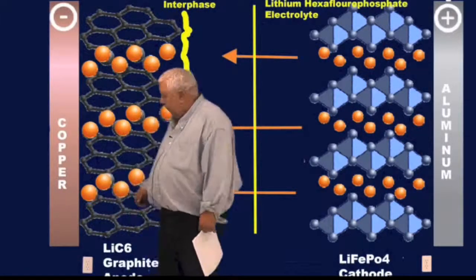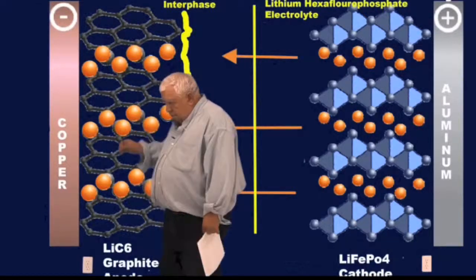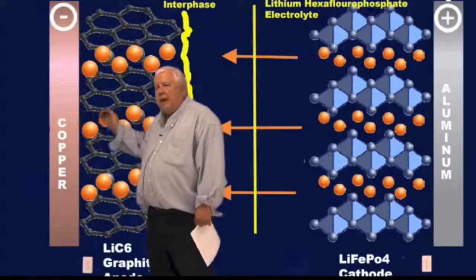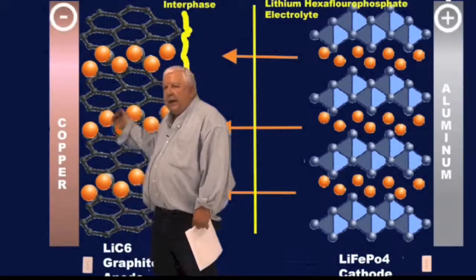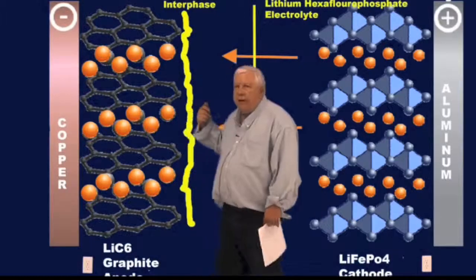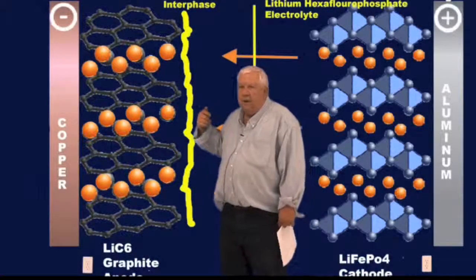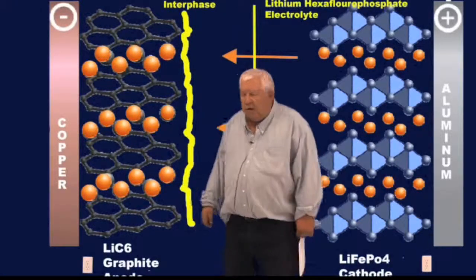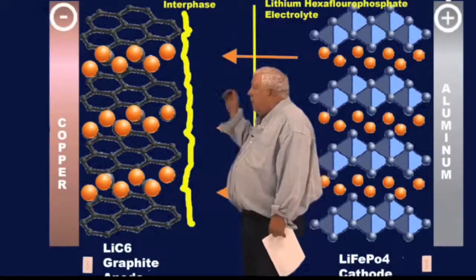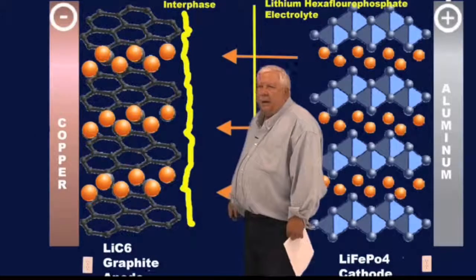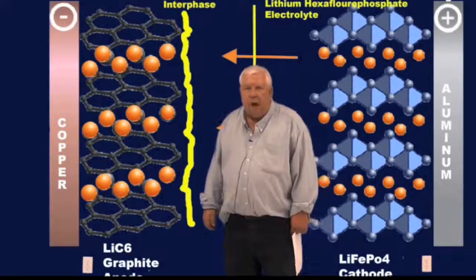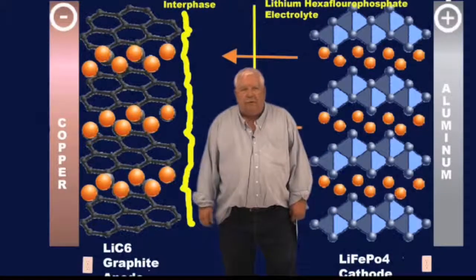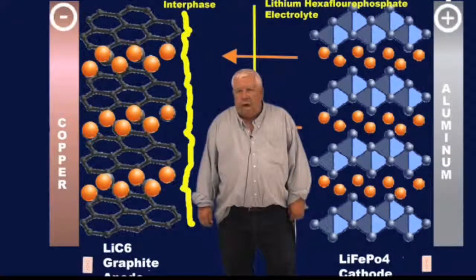A lot of people talk about copper shunts being involved out here. Some, that copper plating can turn into dendrites and again puncture your separator. And if that happens, it shorts the cell. And so you have essentially the same effect on overcharge and over-discharge. Overcharge tends to be a buildup of iron, and over-discharge tends to be a buildup of copper.